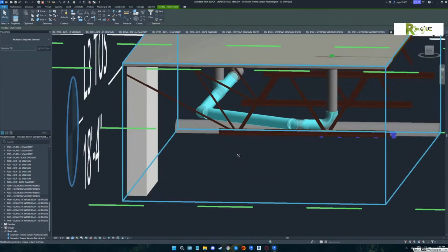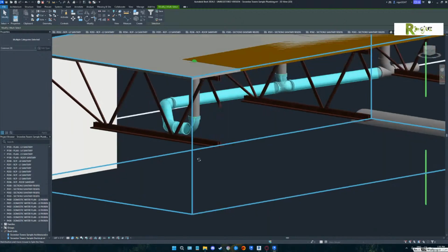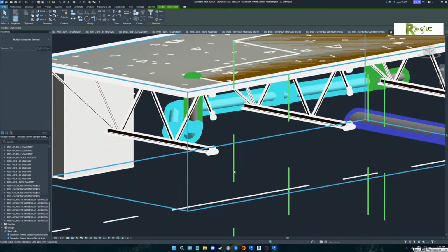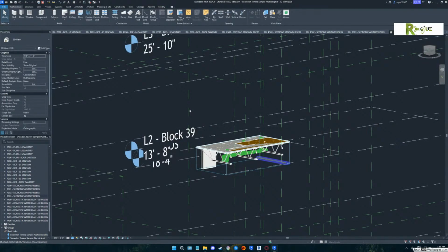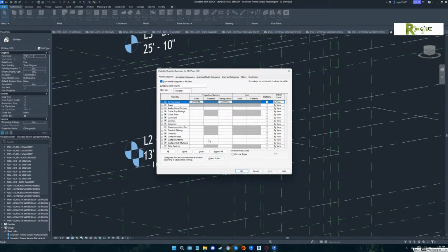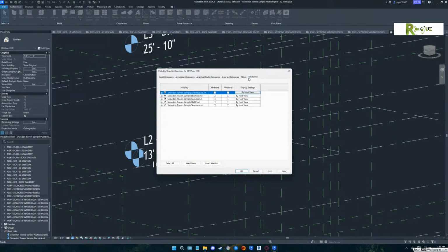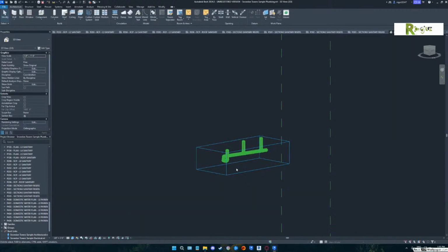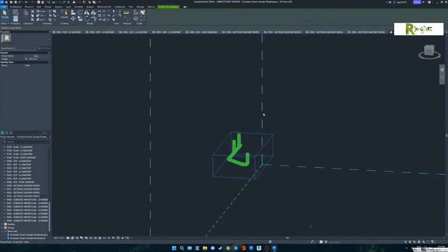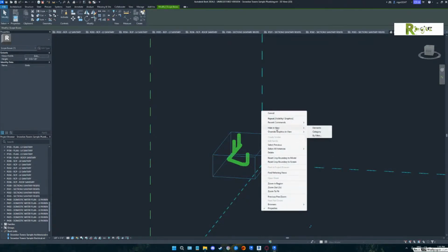You know why that view is looking so ugly again? Because remember what we did was we did a VV and we hid all the Revit links. How do you hide the Revit links? And then the other was the scope boxes. You just hit those in view category, right?